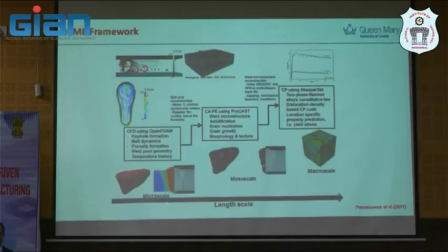And then this is the predicted temperature field. This is the heat affected zone, something like that. And you'll see it's in quite good agreement with the experimental work, validated here. After that, we have the reconstruction of the melt pool. The linkage is so important. We link the temperature contour of the liquid at the surface and the volume of this melt pool. We extract the temperature field of this one, mapping the cooling rate at the boundary here, because everything inside is basically liquid.